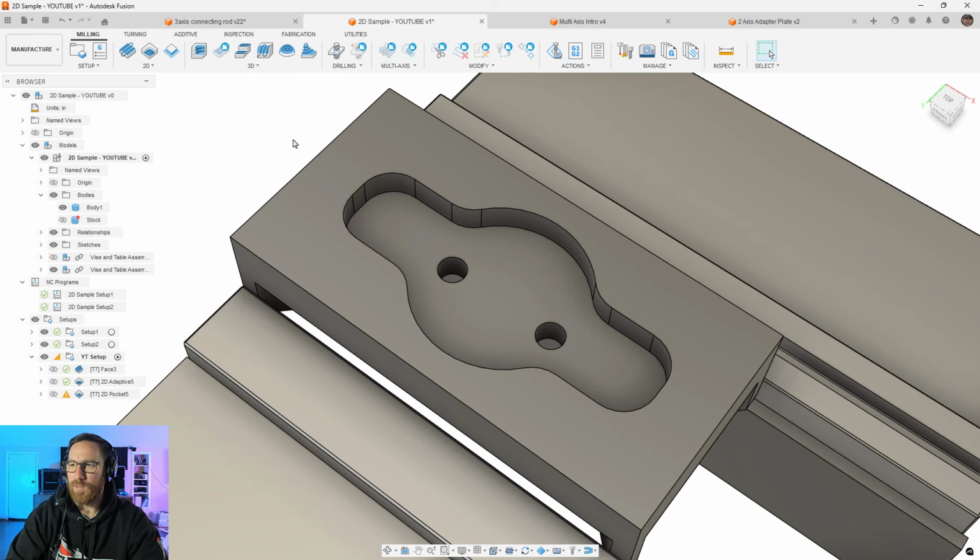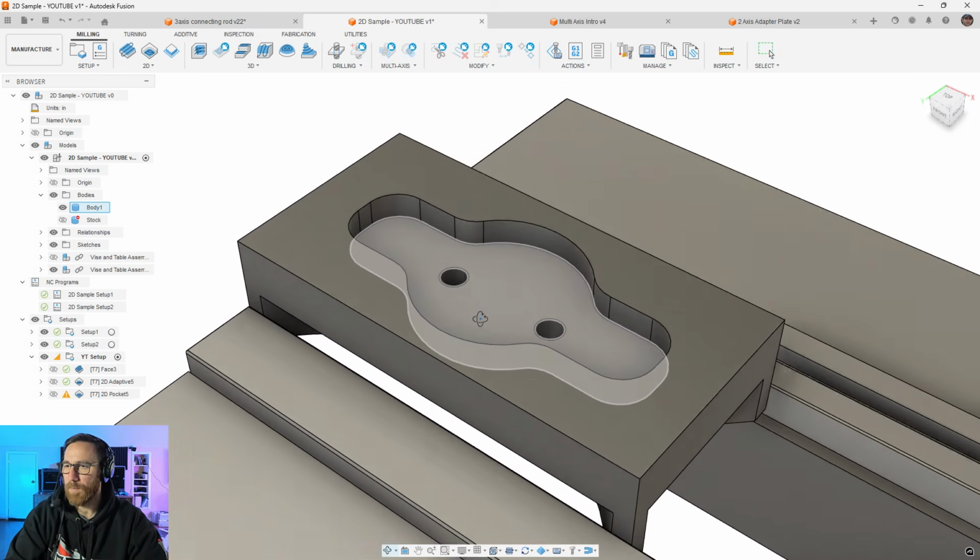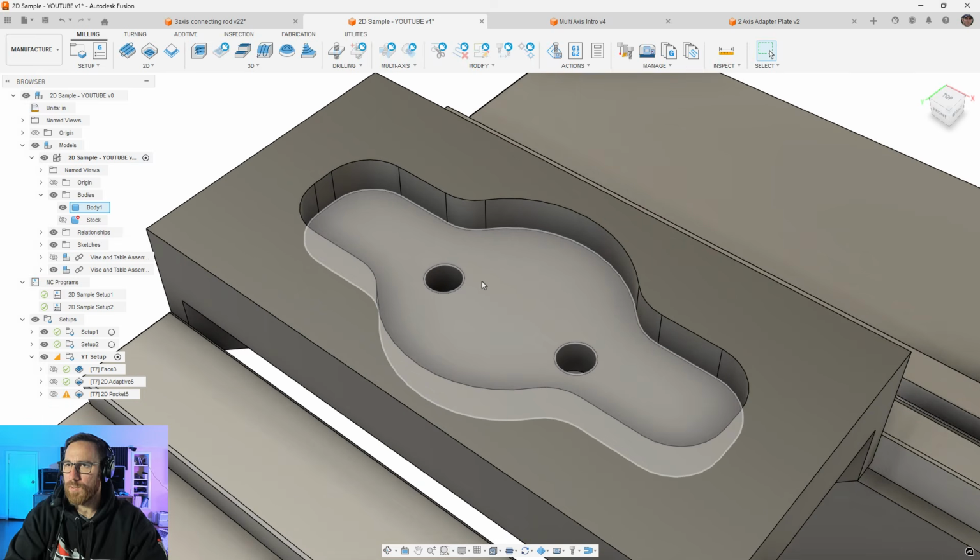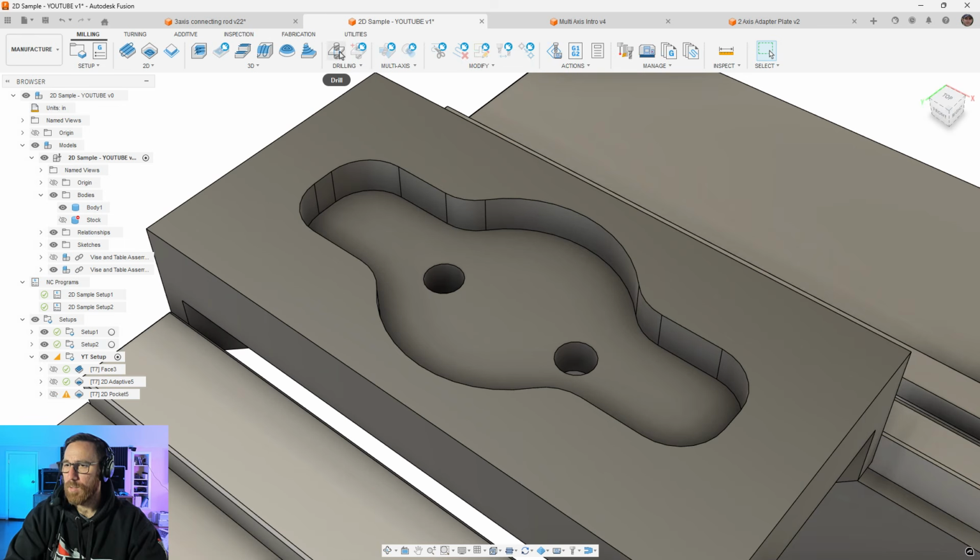Drill bits are going to have a certain range of tolerances for making holes in terms of their precision, and doing things like a 2D bore operation or a 2D contour are typically going to give you a higher level of accuracy to the CAD model. And so what we're going to do here is we're going to start by spot drilling, pre-drilling, and then we're going to do a finish mill.